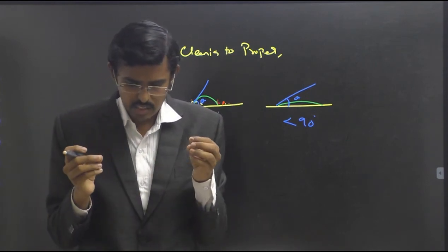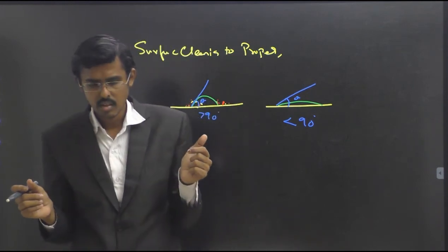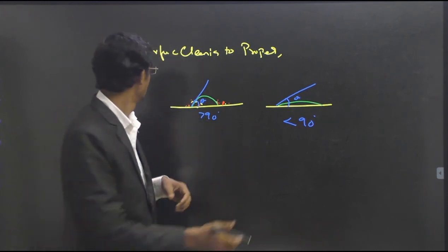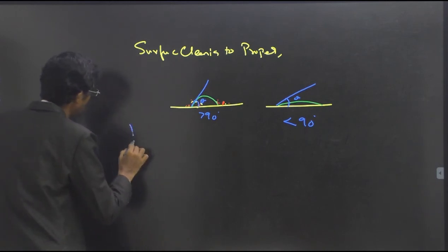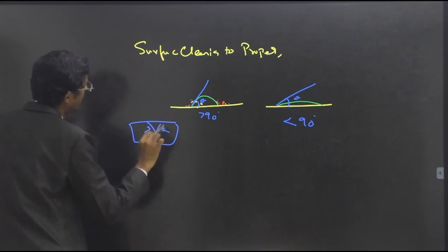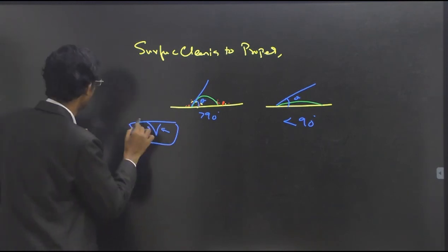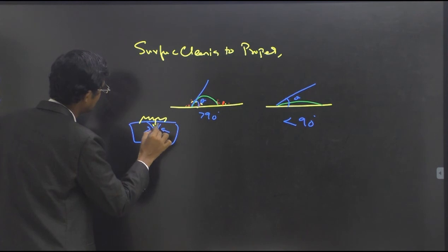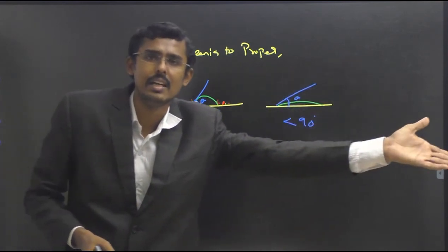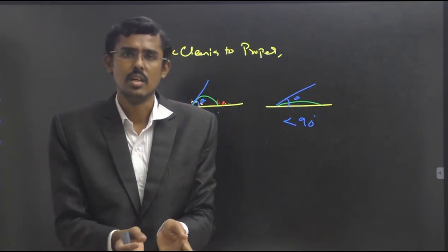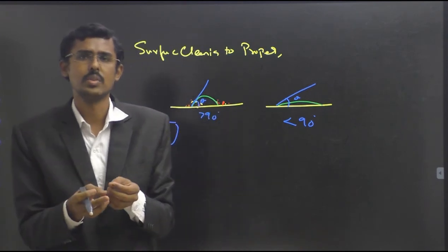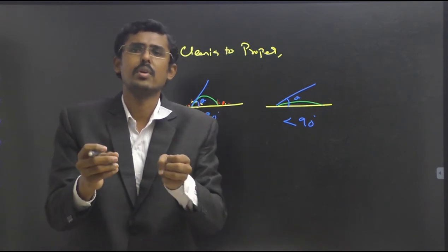So surface energy is involved in the crack surface. The surface energy will drag the liquids. We have talked about this point already. This point and this point have some surface energy which wants to drag the liquid inside, and it is going to fill. So all these things are based upon the contact angle and the surface tension of the surface and the liquid, which all together come under the terminology of capillary force.